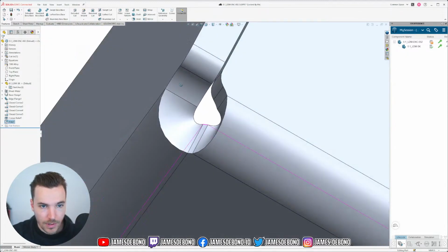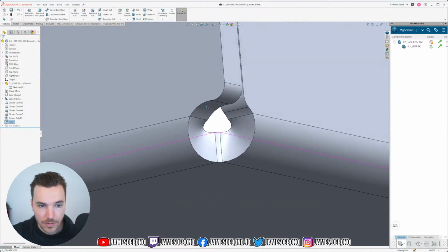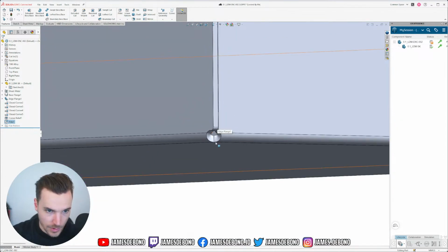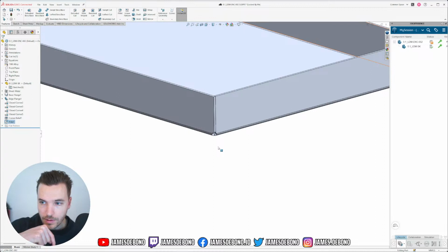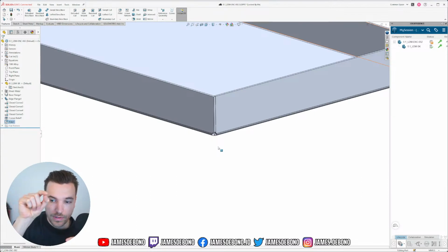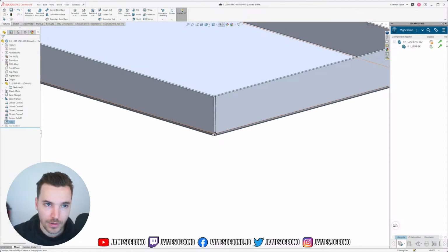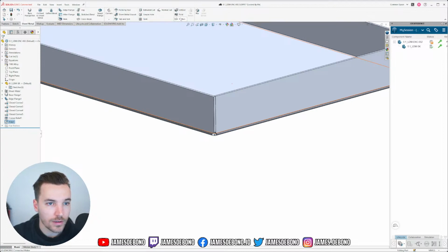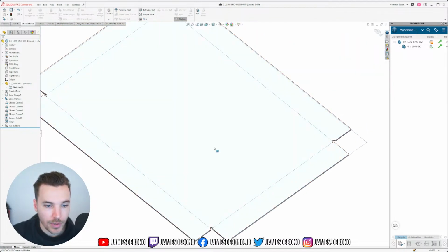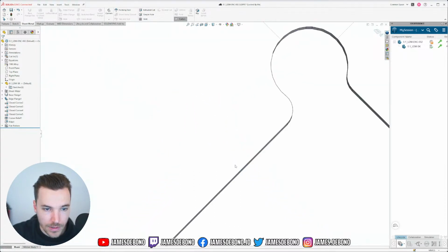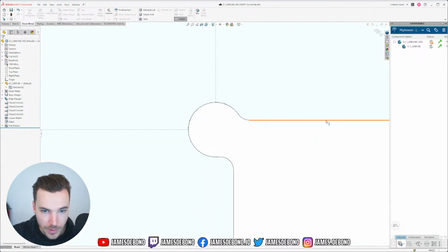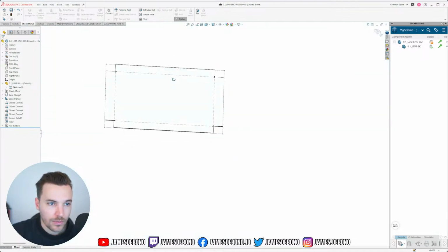Okay, so now I have all curved or filleted edges, which is much nicer for laser cutting, because it means that the laser cutter never has to have a sharp point where it stops and then goes in a different direction. It'll smoothly transition to the different direction, which means you get less vibration and weird stuff happening on the cuts. I can flatten this. This is my flat pattern, and you can see that a laser cutter will have a much nicer time traveling around this smooth curve. So that's pretty cool.